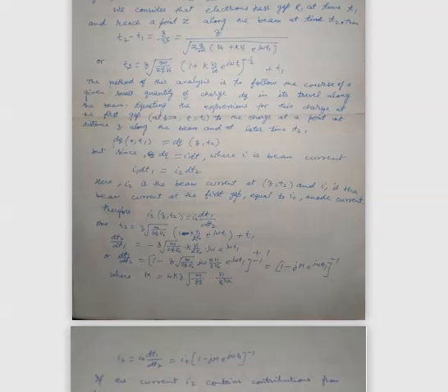Now the time for the electrons to pass from gap R1 at time t1 and along the beam at any time t2, then t2 minus t1 will be given by Z over V, where V is the velocity after the velocity modulation process already discussed in our previous lectures. From this equation, the time t2 may be calculated and is shown in this equation.